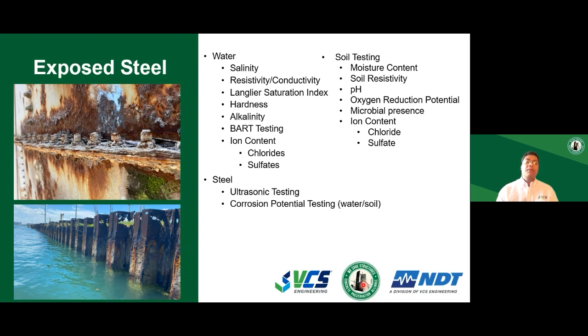of corrosion. But if your concrete structure is exposed to chloride contaminated soils, the concrete will leach the chlorides in. It will take the chlorides from the soil and it will cause corrosion of the steel. There is a big potential for that. And we have seen that happen over and over again because concrete is porous and it will absorb anything and everything that comes in contact with it. Chloride in the soils is one of them.